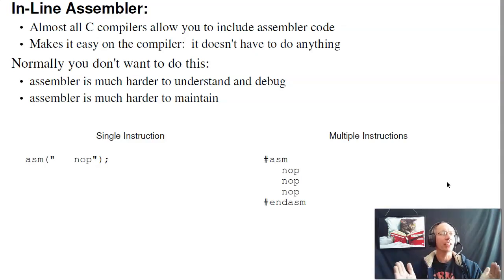If I have a real-time processor and every 10 milliseconds it's got to run through the routine, I write it in C, compile it, and it turns out it takes 11 milliseconds. That's not going to work. I need to squeeze down the code in speed. So what you do is find out which routine is being called the most, and handwrite those in assembly. That'll speed it up. Try to squeeze it down so it fits in that 10 millisecond window. Sometimes you have no choice but to write your code in assembly. It's really frowned upon, it's really not desirable, but sometimes you've got to do it.